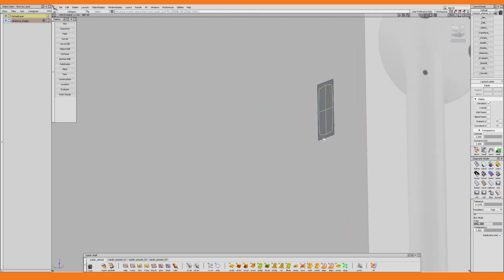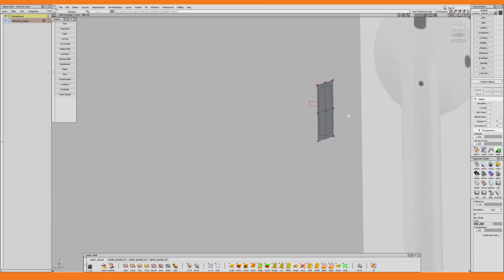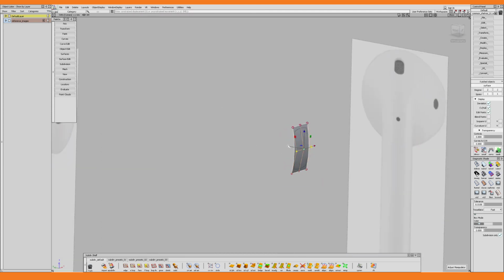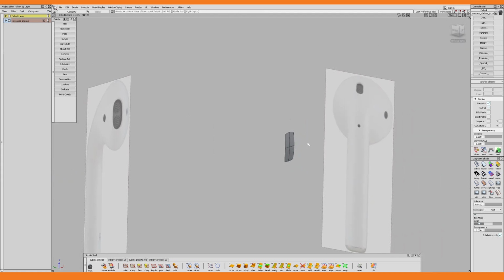If I disable the controls for the subdivision object, and then turn on the hulls and CVs for the help surface, I can then use this help surface to shape the subdivision object. When I'm happy with the changes I made, I delete the history for the objects, and then I delete the help surface as well, since I don't need it anymore.